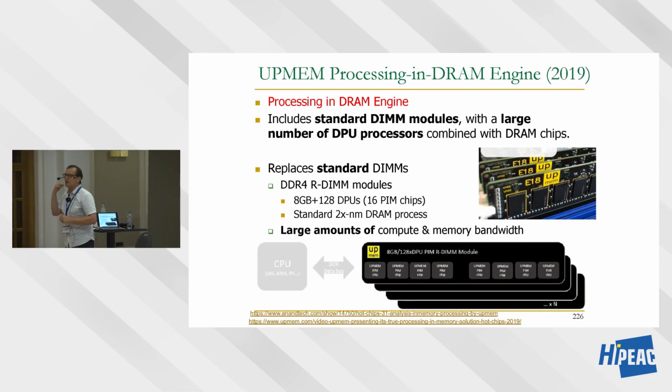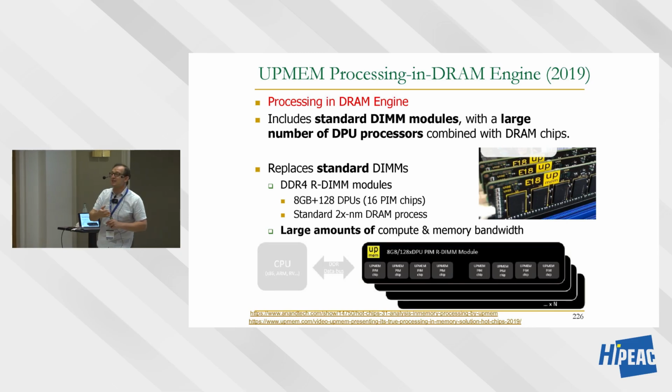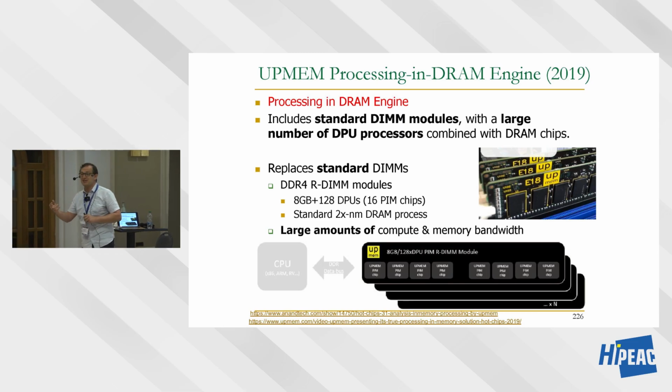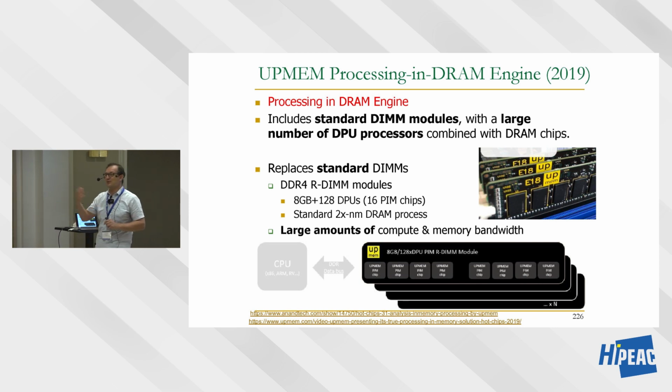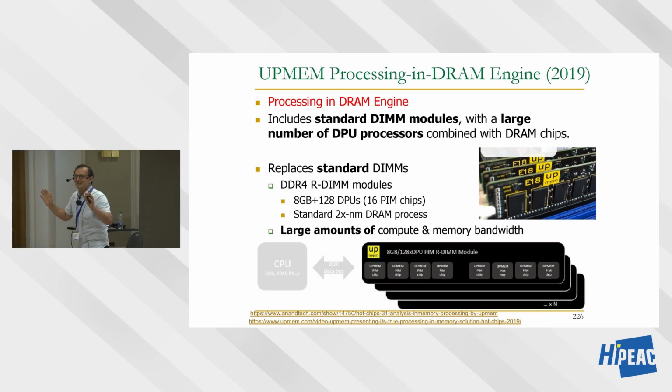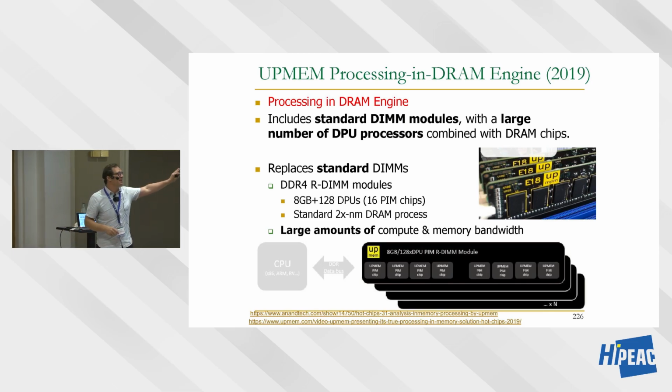And the other thing is, there are some design choices over here that I don't want to pick on, but the instruction set doesn't support multiplication instructions that are larger than the granularity of 8 bits. So the best you can get is 8-bit multiplies. If you want to do 16-bit multiplies, it's a lot more costly. If you want to do bigger multiplies, good luck. So basically, this is not good especially for workloads that exercise multiplication a lot. And there are some workloads like that, as you may guess. Like machine learning, right? But of course, if you reduce machine learning so that your multiplications are smaller, that's a different thing, right?